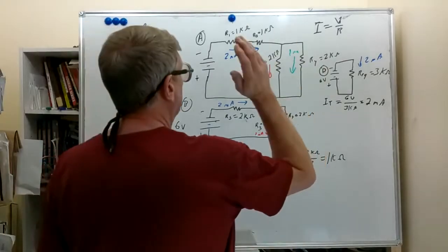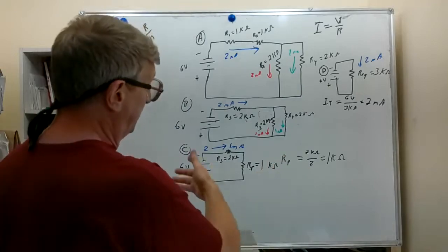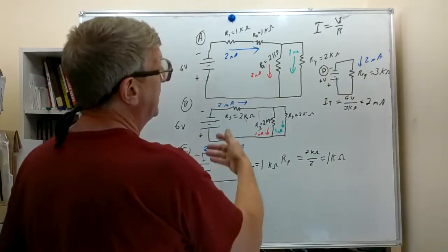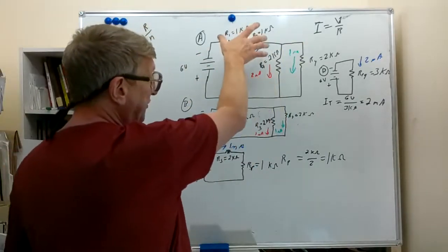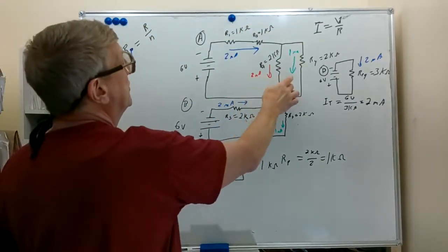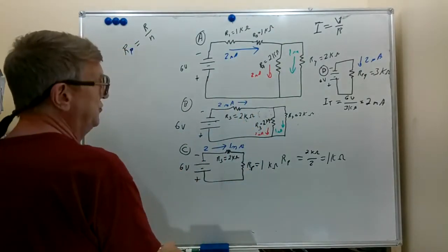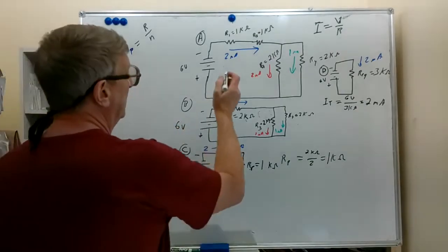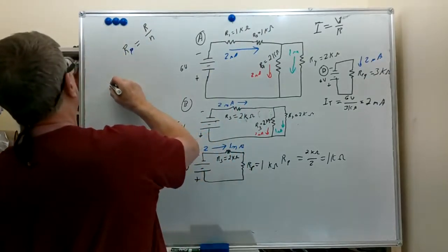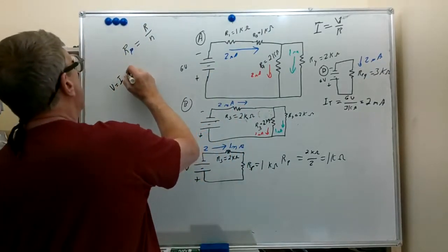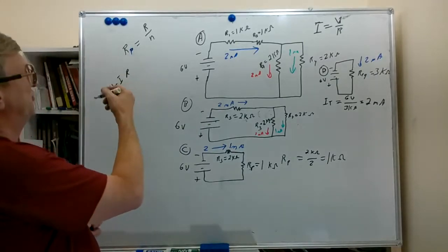And we used our Ohm's law, I current is equal to voltage divided by resistance, to solve for current. And we worked our way back, we looked at how to divide it, and here we have our original series and parallel circuit with all the currents in each position. And just for kicks, let's quickly do the voltages across each of these. So R1, remember, voltage equals I times R. And when I is in milliamps and R is in k ohms, voltage is in volts.